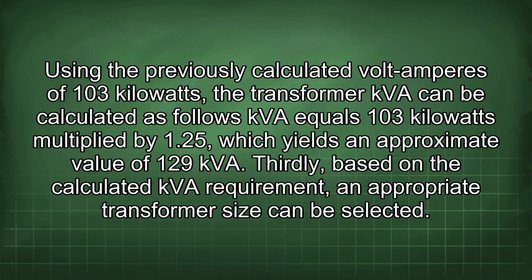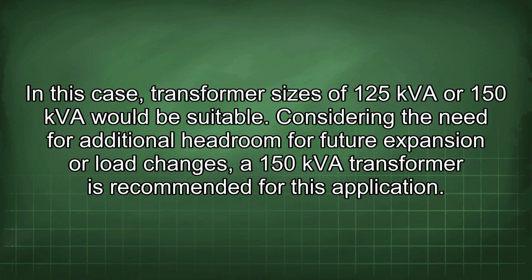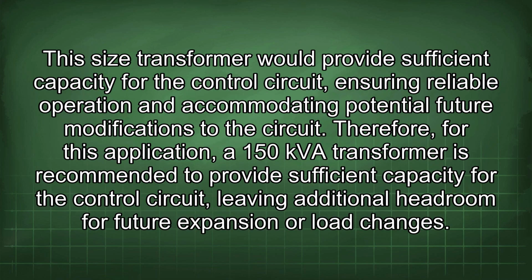Thirdly, based on the calculated kVA requirement, an appropriate transformer size can be selected. In this case, transformer sizes of 125 kVA or 150 kVA would be suitable. Considering the need for additional headroom for future expansion or load changes, a 150 kVA transformer is recommended for this application. This size transformer would provide sufficient capacity for the control circuit, ensuring reliable operation and accommodating potential future modifications